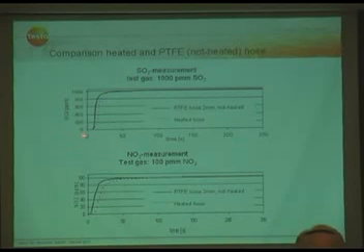But another thing, because of our high gas flow, the high velocity inside, the reading is very fast, faster than using a heated hose. This is in some applications also a big advantage if your reaction time or your response time is very fast. And here, especially NO2, you can see the difference. There is a few seconds delay comparing the heated hose with our Teflon hose.